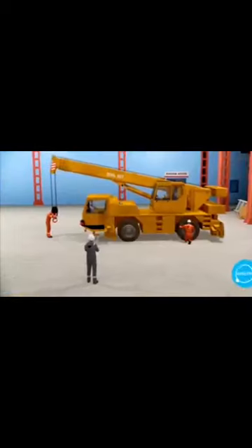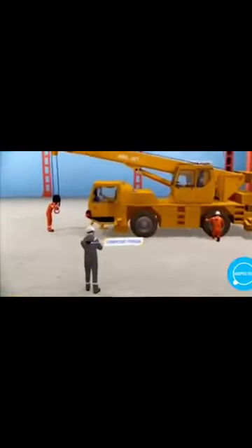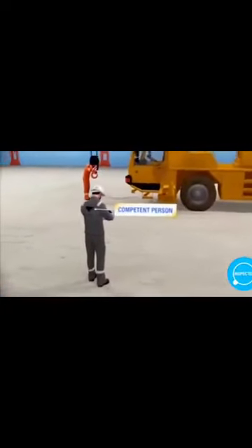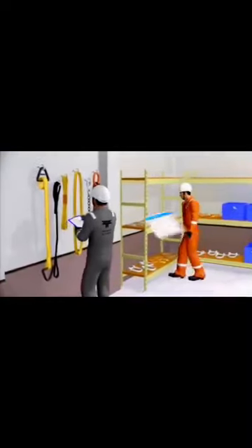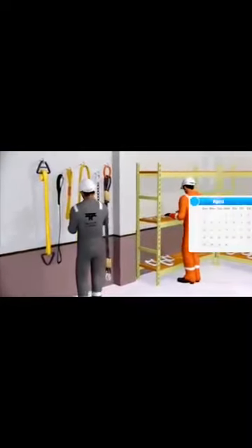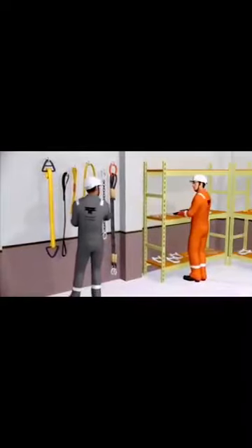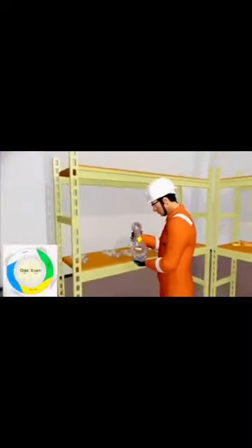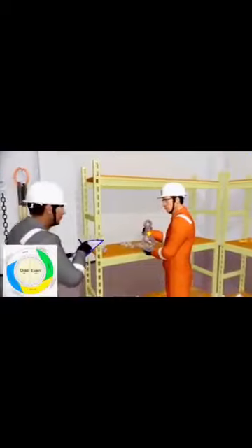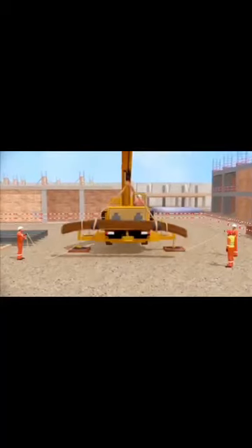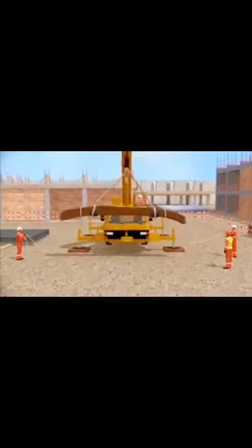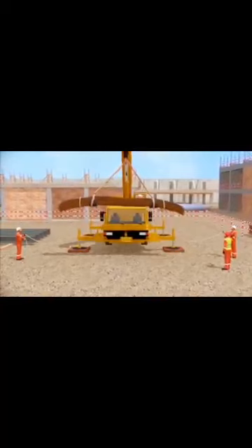The equipment should be inspected by a competent person, and the certificate must be kept safely. All the lifting equipment should be checked by a lifting equipment controller every month, and it shall be inspected and color-coded as per the current month's color-coding practice. Every lifting work to be carried out should be pre-planned and shall be conducted under the careful supervision of a competent person.